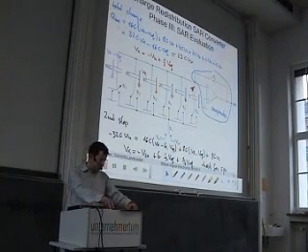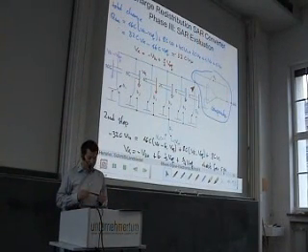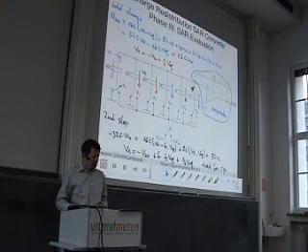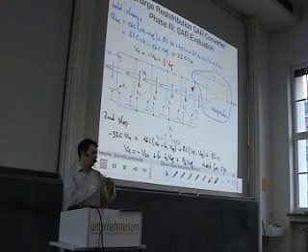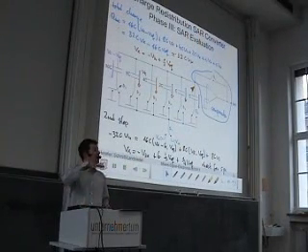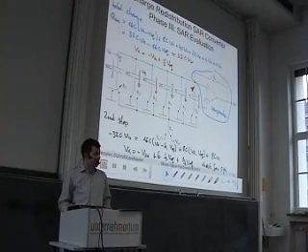Of course, this binary search principle is not limited to this charge redistribution converter. You can also imagine that you take a resistor string to generate all possible voltages, and you use a binary search technique to search within this resistor string.